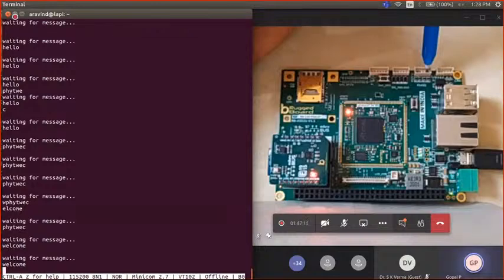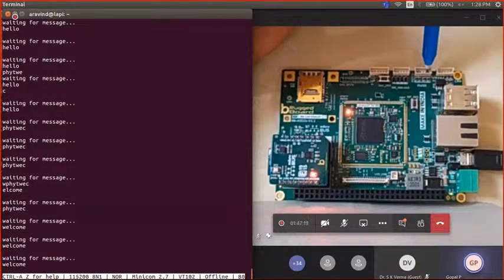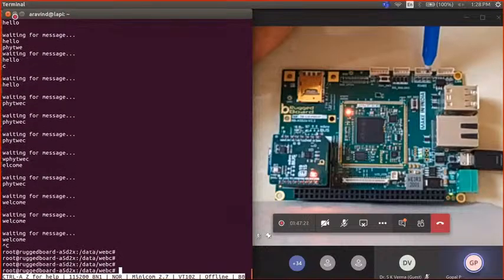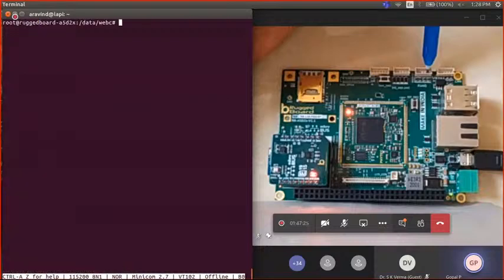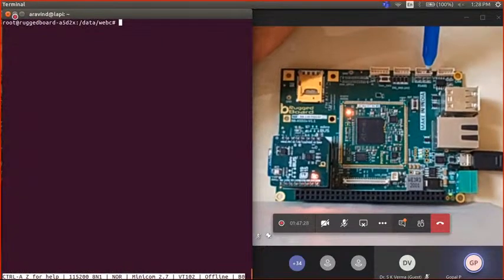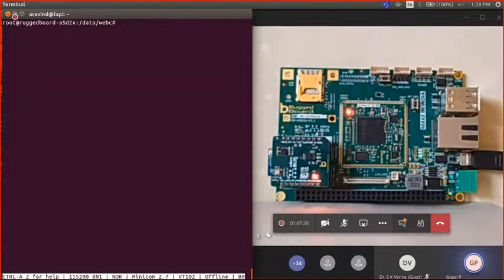One you can connect to the GSM, one to the GPS, or Zigbee or Bluetooth if you want to send the data locally. From the GPS we get the latitude and longitude, and we push it straight away to the local server itself. That's one of the beautiful applications we can do using this UART peripheral.